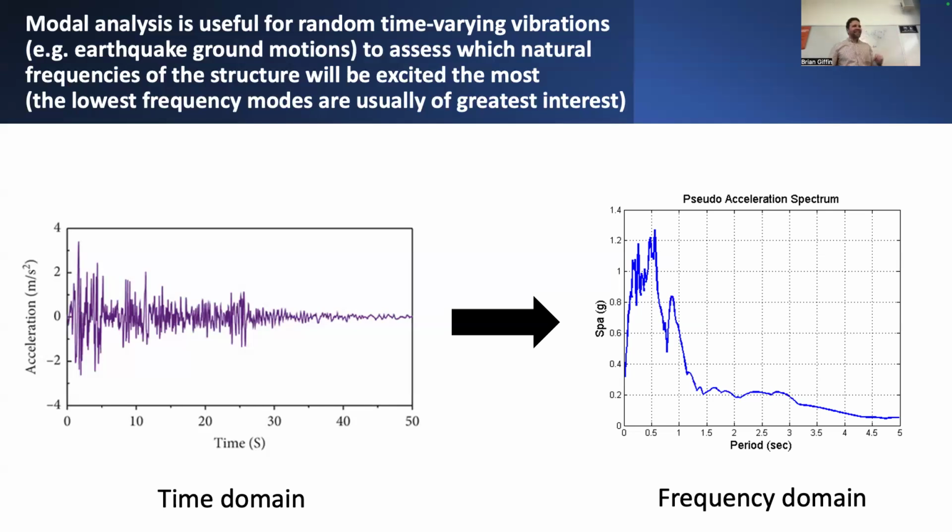So if that's the case, and you really only care about these low frequency modes of deformation, you don't need a super refined mesh to do it. You really just need to identify the relevant modes of deformation of interest, and then figure out how the structure is going to behave in those specific modes. So that's the idea behind modal analysis. It's sometimes nice if you know that there are certain modes of deformation that you're worried about, that the structure might start to vibrate at if it were to have an excitation that matches the frequency of those particular modes of vibration.